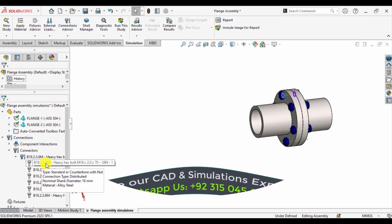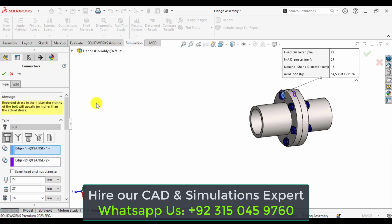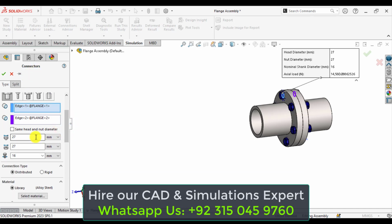Right click any connector and go to edit definitions. So here are the bolt connector details, where it describes the bolt diameter, nut diameter and also the shank diameter. Also ensure that alloy steel has been assigned from the material library.